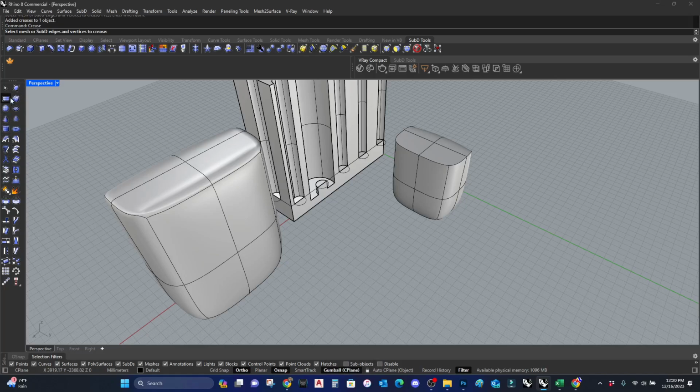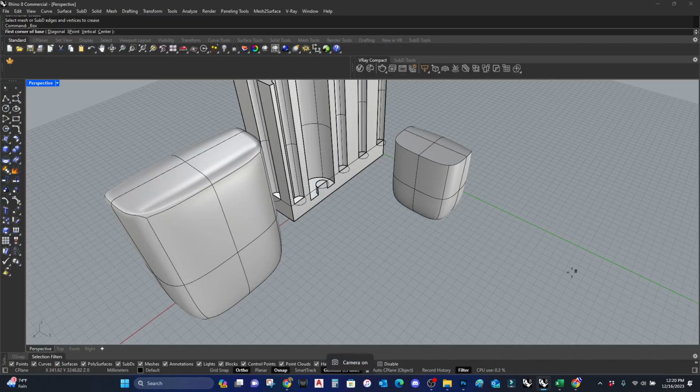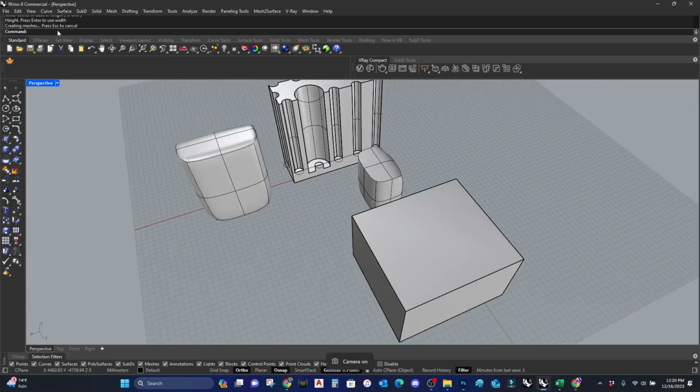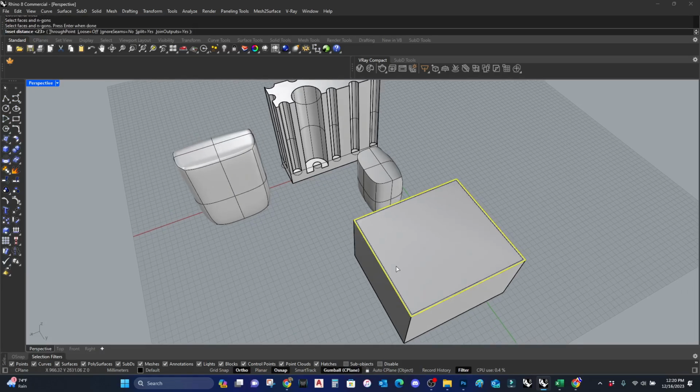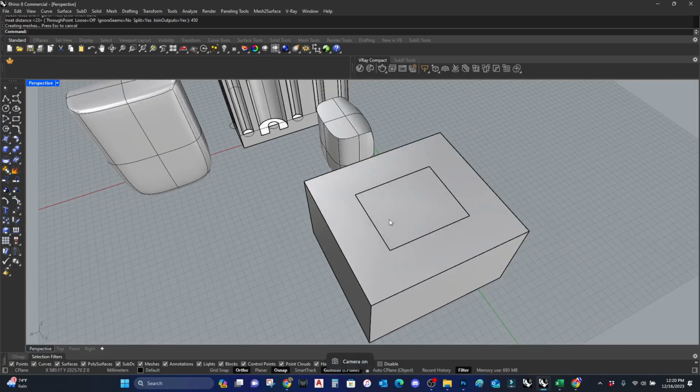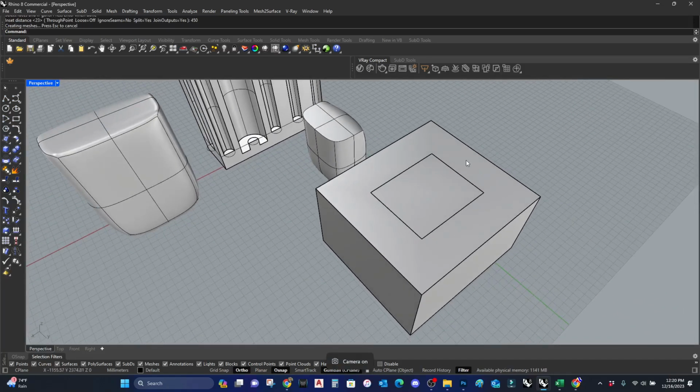Another good command that I can show. Let me go to standard. Let me make a cube, and you can create offsets within curves in this object. So let me type in inset. I'm going to select the surface, and it's already giving me a default for the offset, which is 23. Let me increase it to 450. And now you can create an offset with these curves.